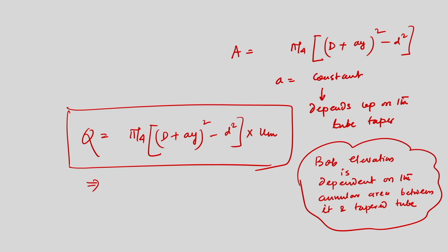It is also important to note that our measurement should not have any bias, should not have any dependence on the fluid density as well. If we need to ensure that the measurement process using this rotameter should not have any dependence on the density, this is an advantageous feature, and that can be obtained by doing a small calculation. How? Because we have calculated the volume flow rate.